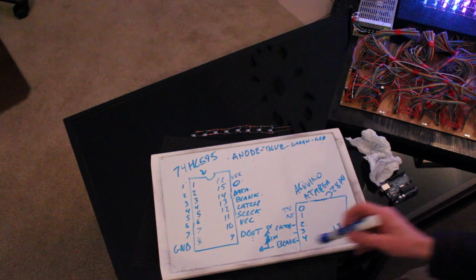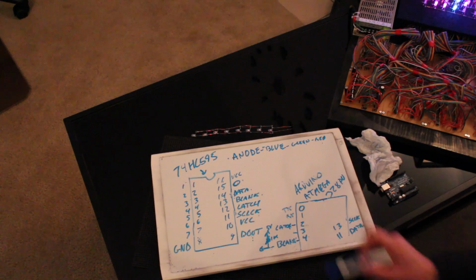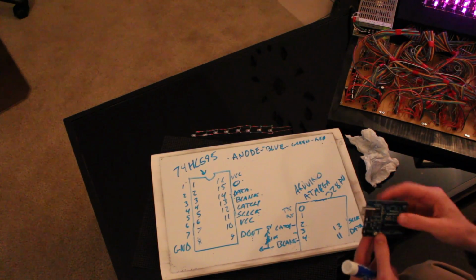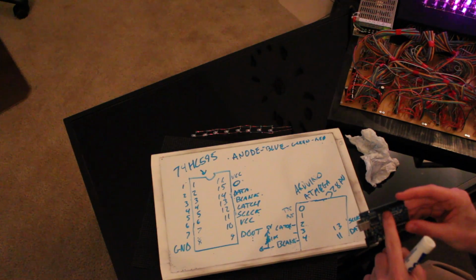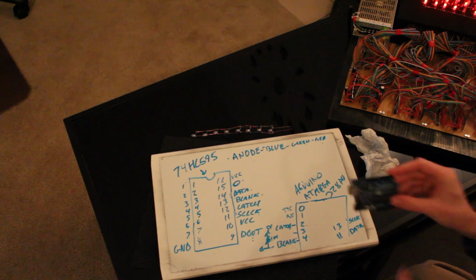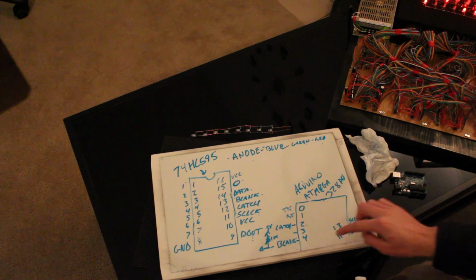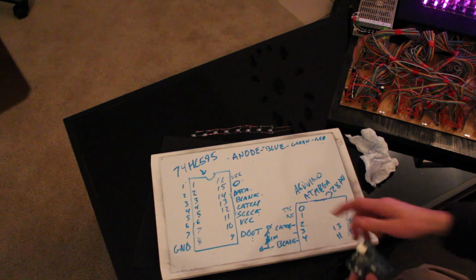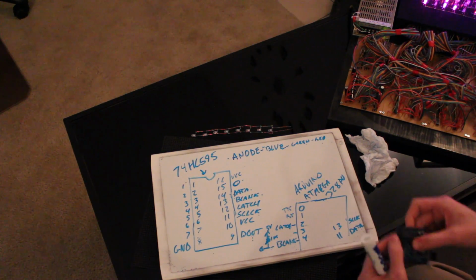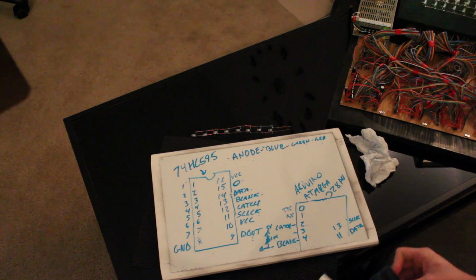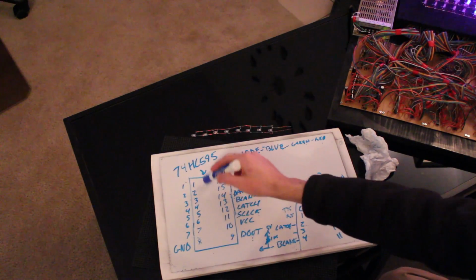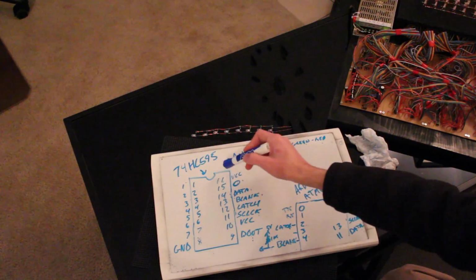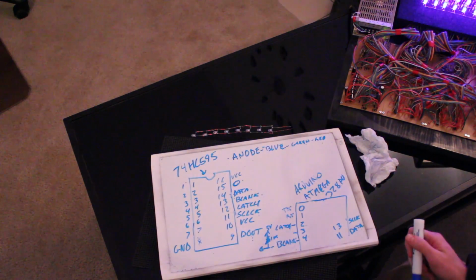And here's the Arduino over here, and these pins refer to the Arduino pins. When you look here, you'll see pin 0 keeps counting all the way up to 13, and that's what I'm showing here. These pins do not correlate to the physical pins. When you hold the chip up and count from the top left around counterclockwise, it's not the same thing.